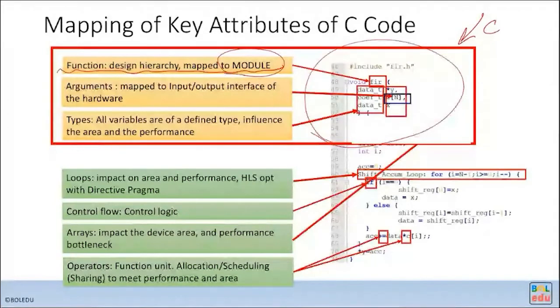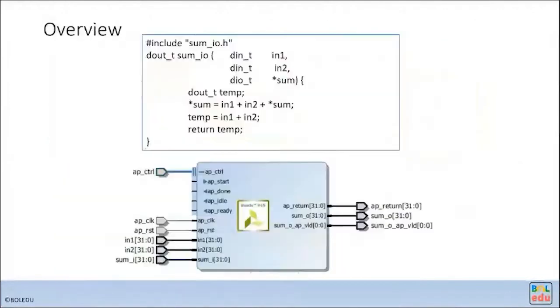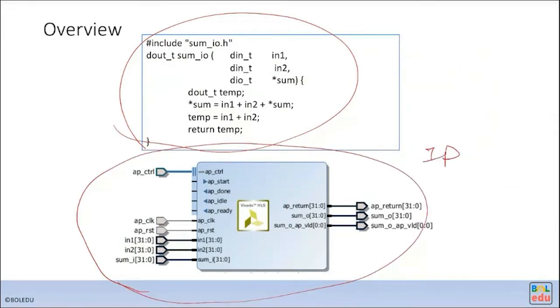Okay, this gives a very simple example. When you take these modules and go through HLS synthesis and IP generation, eventually you will get an IP like this one. First, you notice there is an AP control protocol. There are some signals generated for controlling the block. This is the block-level protocol. And for the others, the port-level protocol includes the data ports and certain control signals or